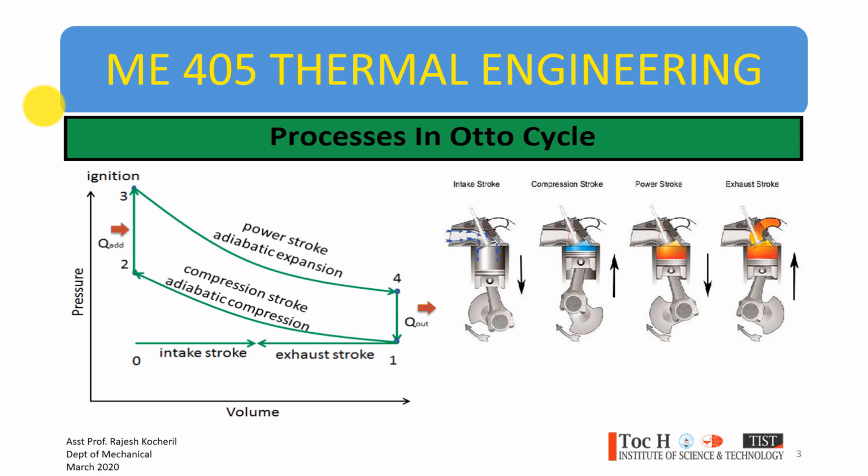Now, during this period, the air-fuel mixture passing through the inlet valve is denser than the hot flue gas inside the cylinder. So this denser air-fuel mixture will push the hot gas out through the exhaust valve, additionally with the movement of the piston from BDC to TDC. And this will ensure that proper scavenging takes place, and that the hot flue gas is out